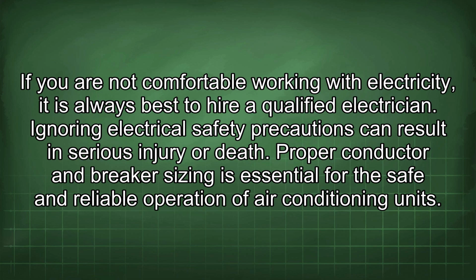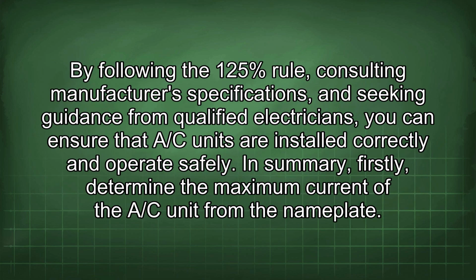Proper conductor and breaker sizing is essential for the safe and reliable operation of air conditioning units. By following the 125% rule, consulting manufacturer's specifications, and seeking guidance from qualified electricians, you can ensure that A/C units are installed correctly and operate safely.